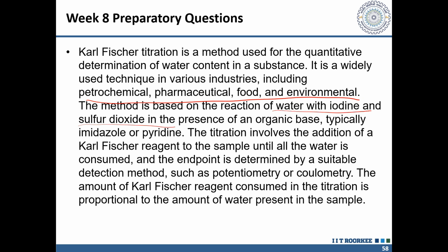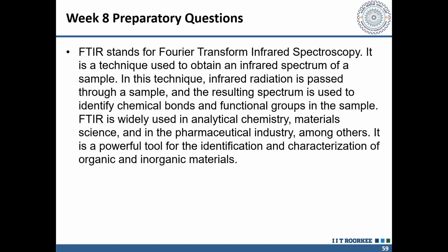So the higher the iodine requirement, the higher the water content it will have. So it's a typical titration method, whereas FTIR is a different method. It is a kind of spectroscopy. In this, we place a drop of liquid over the diamond crystal, and infrared rays are passed through the oil.